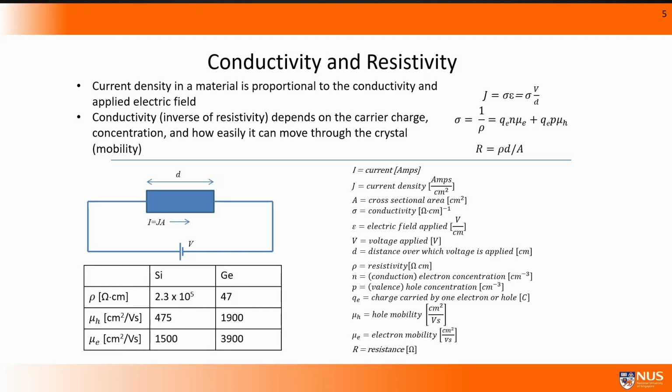Because when you look at this, all these variables, there's Greek letters, a long list of terms, what I'm always worried about is that if I go to this immediately, you might look at it and say, my goodness, look at all this mess. But in fact, the current flow in a bolt of lightning is very similar to the flow of current inside a material. And it really only depends on these 3 things: the number of charge carriers, the mobility, and the applied voltage.